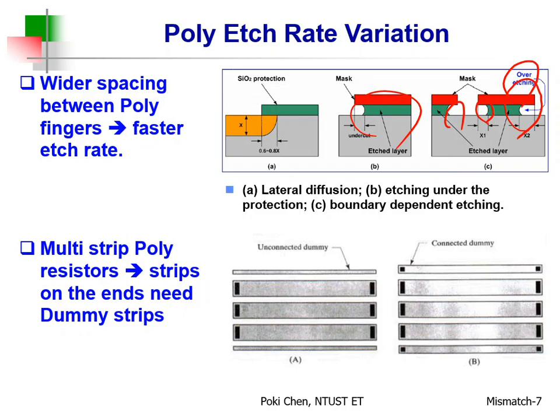Then we have 2 plots for you for comparison. 3 resistors to be matched. All right, 1 and 2 and 3. Okay, you say, hey, look, I have dummy. Oh, very good. You also have dummy, right? Also very good. And how about the key rule? How about the golden rule? The spacing here will be the same as there.